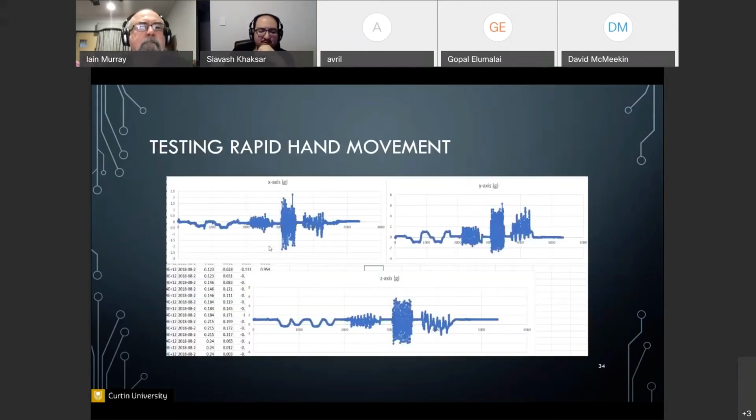Another interesting test I was doing during my research that might be relevant here is looking at the maximum range of G that I could have for my accelerometer. At the beginning of this research, the scale we had set for our G was set at 2, and we were assuming that would be enough for the small movements.